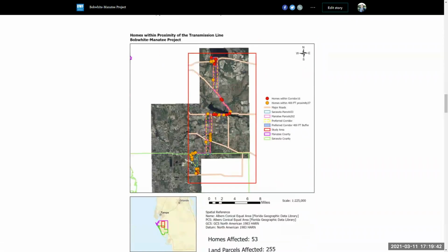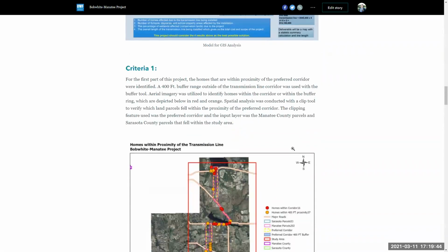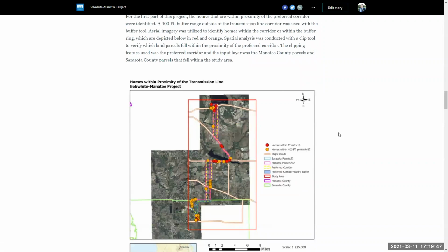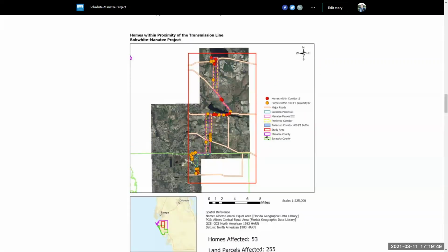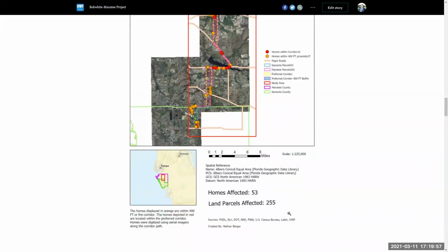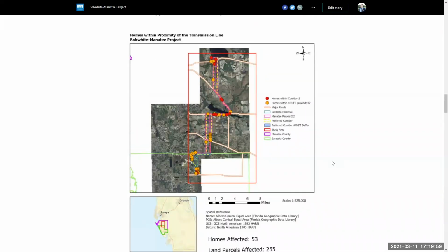And I have a little written summary here outlining what we're doing for this. So what I started doing is I took all of the imagery required for the project that was collected from Lavin, and I had to define the projection for a coordinate system for each imagery file. That way, when you start doing measurements and analysis, all of your mensuration is going to be accurate to your local projected coordinate system that you have for your map. So I actually built a little model to do that.